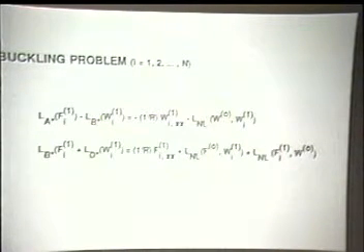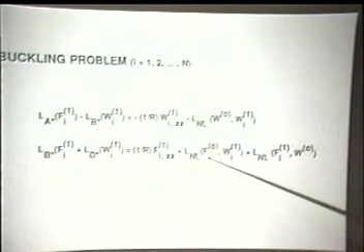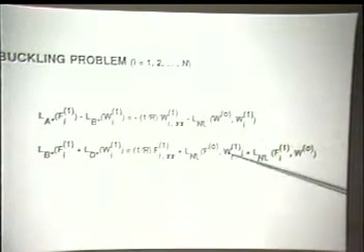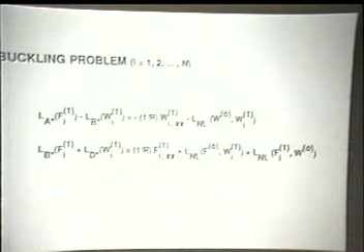The easiest way to solve them is assuming that the pre-buckling state is membrane. Then these quantities are constants, and since these operators always imply second derivatives, their contributions here disappear with the exception of the load term. And then you have, for the stability problem, equations that are constant coefficients, which are considerably simpler to solve.